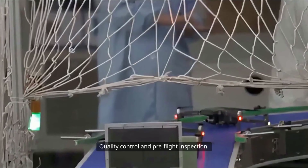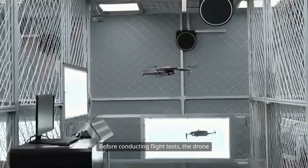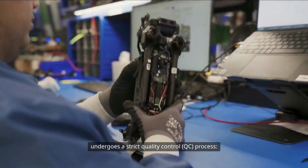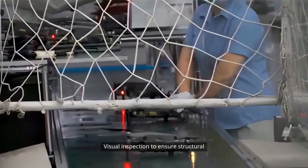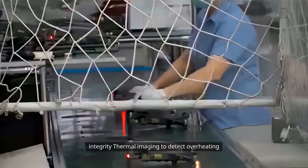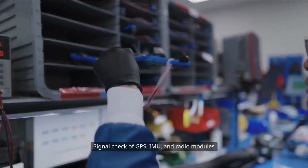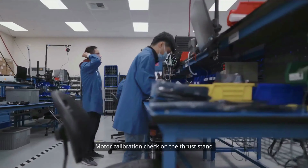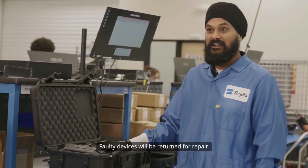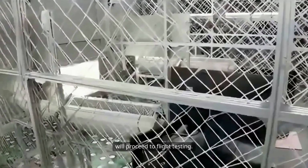10. Quality control and pre-flight inspection. Before conducting flight tests, the drone undergoes a strict quality control (QC) process. Visual inspection to ensure structural integrity. Thermal imaging to detect overheating. Signal check of GPS, IMU, and radio modules. Motor calibration check on the thrust stand. Faulty devices will be returned for repair. Only drones that meet all criteria will proceed to flight testing.